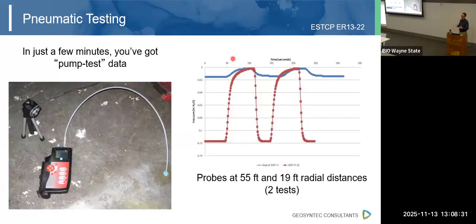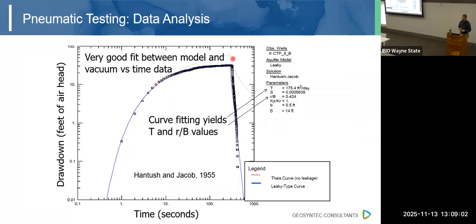So, we can do the equivalent of a pump test in hydrogeology with this high volume sampling approach. We'll have our suction point in the floor, but then we can drill other holes at various distances away from that. We can get a sense of the static vacuum. How does vacuum change as a function of distance from our point? Then we can also cycle that shop vac on and off and get pump test data, look at that vacuum over time. And then we can use those data, use software available for aquifer characterization, and get those transmissivity and leakage values,